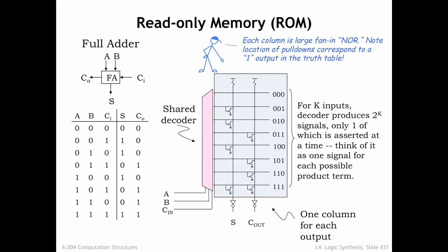The decoder outputs control a matrix of NFET pull-down switches. The matrix has one vertical column for each output of the truth table. Each switch connects a particular vertical column to ground, forcing it to a low value when the switch is on. The column circuitry is designed so that if no pull-down switches force its value to 0, its output value will be 1. The value on each of the vertical columns is inverted to produce the final output values.